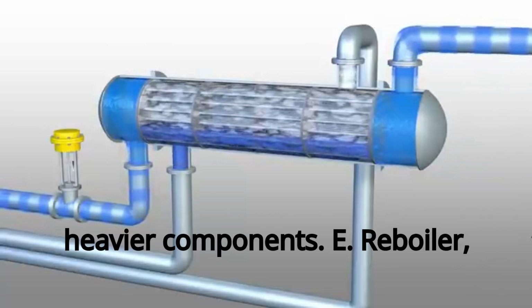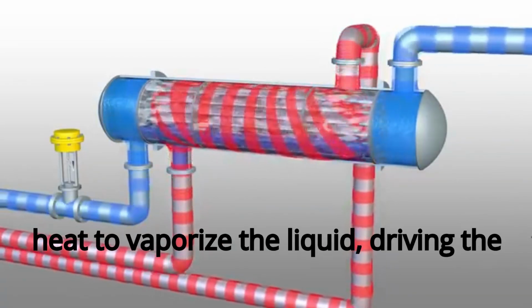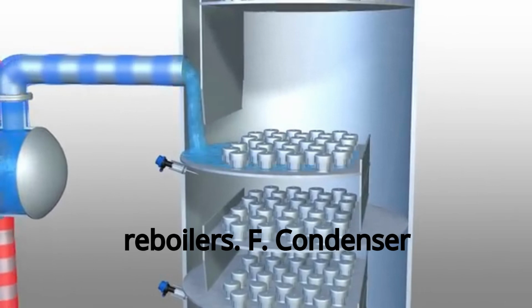E. Reboiler, located at the column's base. Provides heat to vaporize the liquid, driving the separation process. Types include kettle, thermosiphon, and fired reboilers.